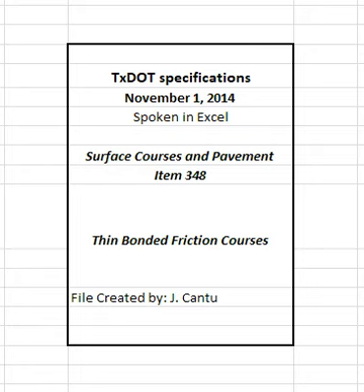2. Materials. Furnish uncontaminated materials of uniform quality that meet the requirements of the plans and specifications. Notify the engineer of all material sources and before changing any material source or formulation. The engineer will verify that the specification requirements are met when the contractor makes a source or formulation change, and may require a new laboratory mixture design, trial batch, or both.